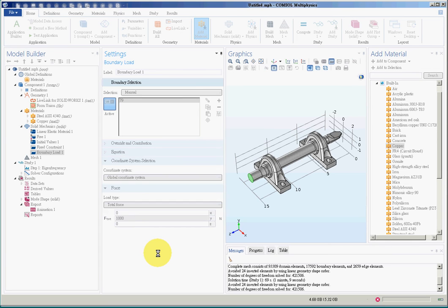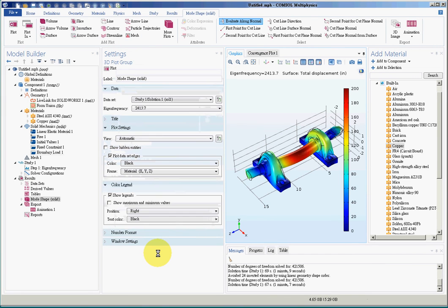So we can see later whether the natural frequency will shift a lot under such an external load. And this is a way to understand how a software is written, so you get more familiar with the software. So you can see that the frequency basically does not shift. It is 1232 under external load.